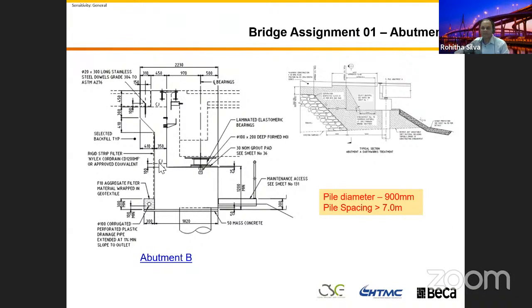Yeah, 4 N20 bars, so 2 layers of N24 bars and 2 layers of N20. That's already 40 plus 50, 90, plus cover 45, 45, both sides. You can see 90, 90, 180 is already in there. So that member you can reduce to an optimum size of 300.